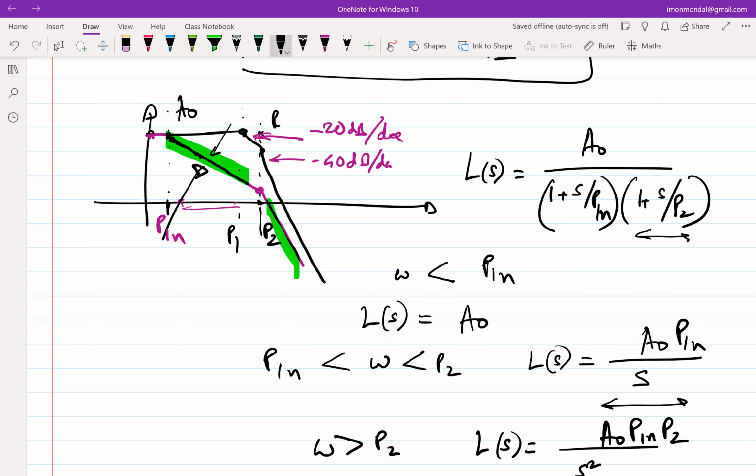Let me quickly recap. What did we start off with? Firstly, we wanted to get a good GM. There was only so much GM we could get using whatever methods we could think of. Then we thought we'd put another gain stage before that GM to enhance the DC gain. The issue is that when you put two of these stages together and close the feedback loop, you can get potential ringing, meaning an underdamped response. It goes up and down, and that is a problem.